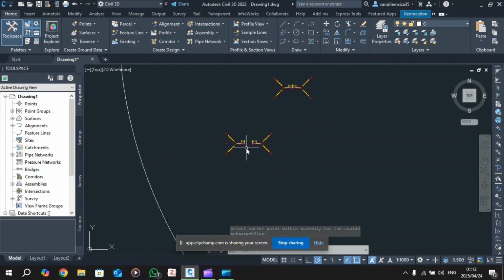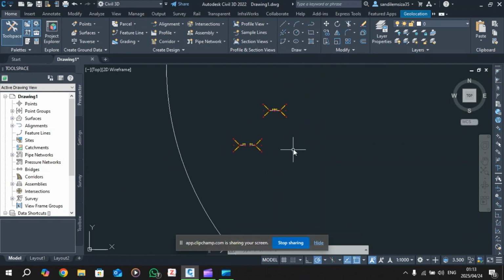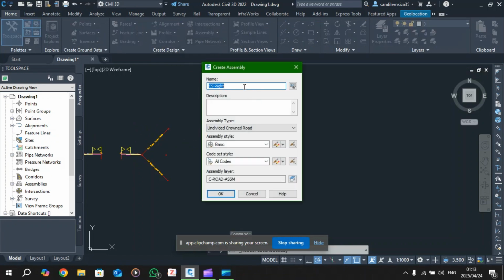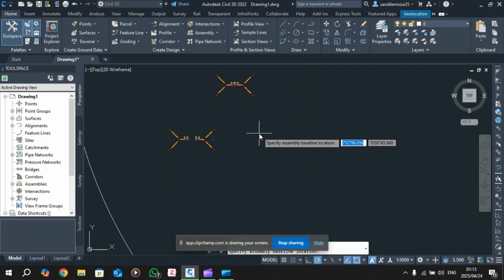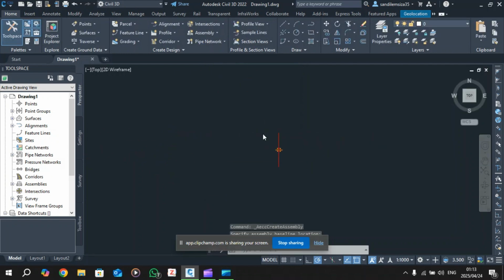Now, our last assembly for now, which we need, is the curb returns, which is responsible for the fillets of your intersection, which again will be focused more in future episodes. So again, we are gonna create an assembly, CS curb returns. Oh, bit of a mistake there. Okay, I'm gonna have it somewhere. Let's have it slightly further over here.